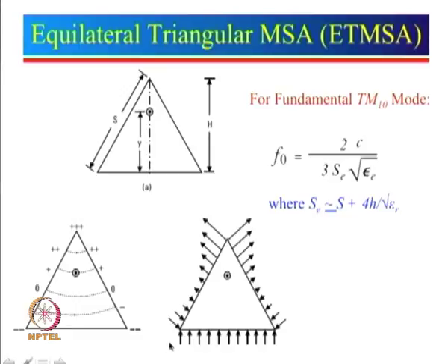Since the amplitude of these is relatively smaller than the amplitude of these here, we can say that the net result will be more amplitude in this direction, and there is another slot, which is this one, that has a larger amplitude. So, these two effectively act as slots radiating in this direction. The pattern of this one will be again similar to that of a circular or rectangular patch, except that the way we have chosen the feed point, the E plane will be in this direction here.